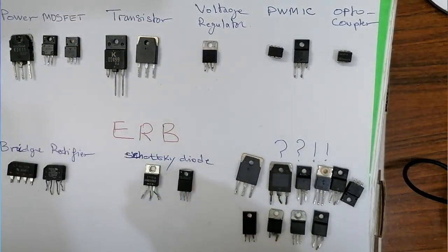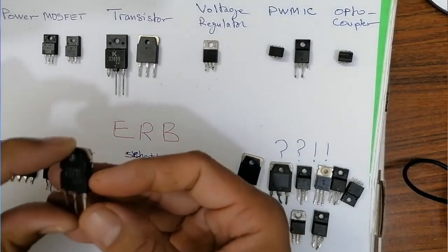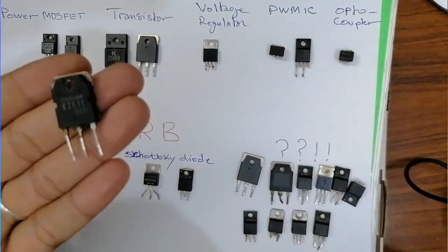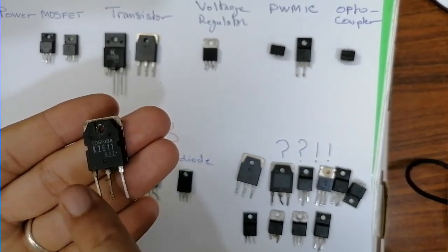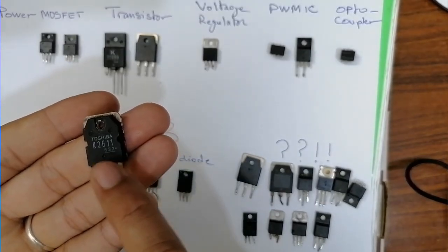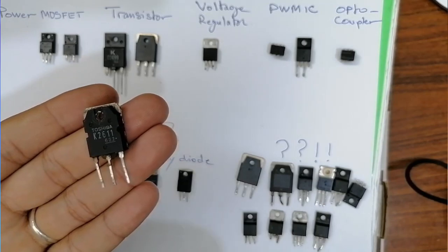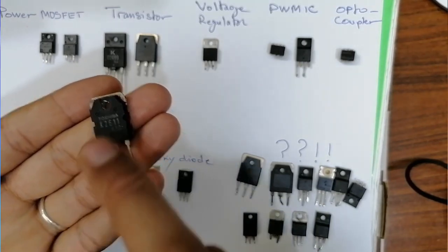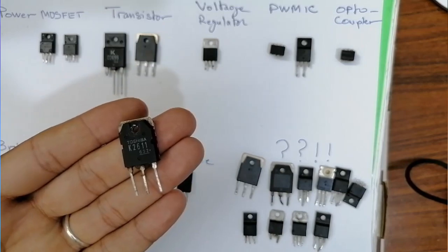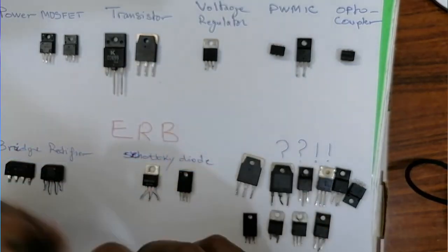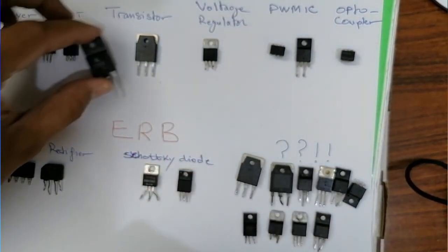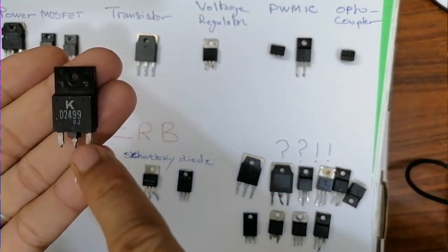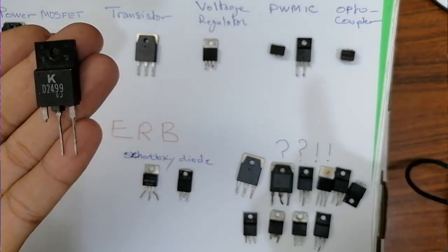By experience, for example, for me, when I see this number, as you can see over here, K2611, the component that begins with this number, based on my experience, is always a MOSFET. Okay? And others, for example, that begin with D24, as you can see, like this one, is a transistor, not a MOSFET.